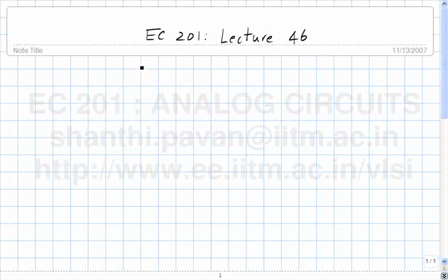So to continue on to the next topic, as I said, the preliminary motivation for a lot of the early op-amp work was to use the op-amp in circuits to get rid of inductors. The reason you needed large inductors in those days was that you were targeting a telephone system and you need to filter off the input signal beyond about 4 kilohertz. Let's first see one way of emulating or simulating an inductor, making the input impedance of a black box look as if there was an inductor inside without actually having one.